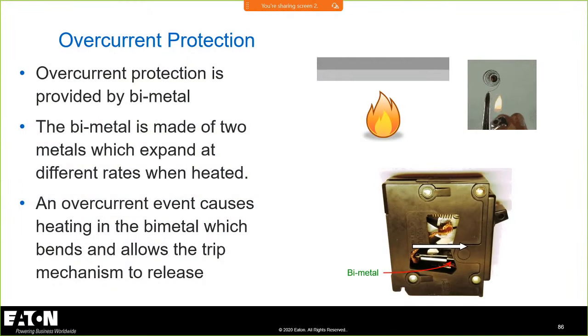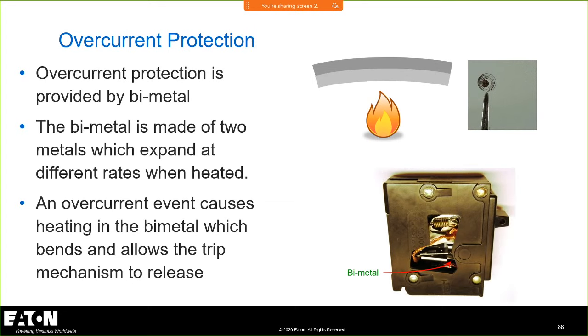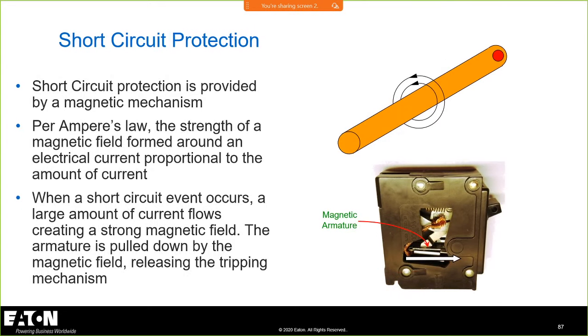All right, so basically what's happening is we're heating a bimetal that's going to bend and turn and cause that coil to trip, just like you saw. And that's the thermal side of the picture. And then on the instantaneous side, you're causing a very high fault current to flow through, and it pulls in the circuit. I lovingly call it the clapper, and it basically will cause it to trip very fast.